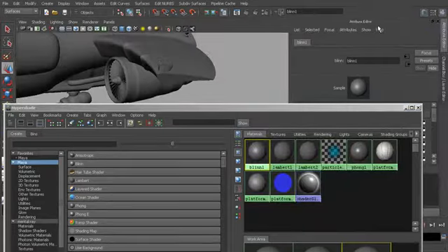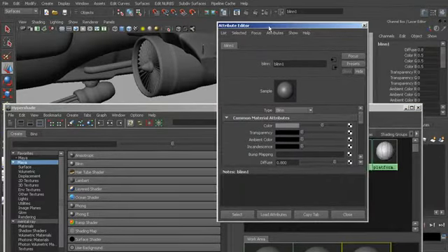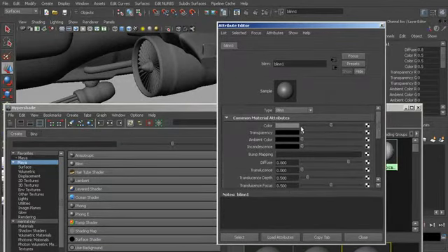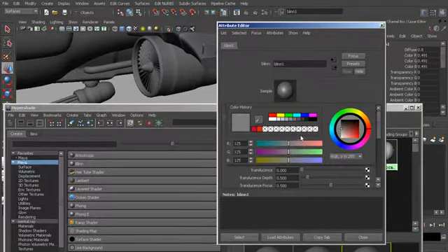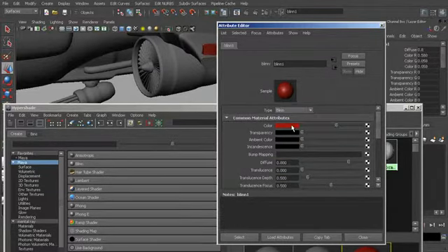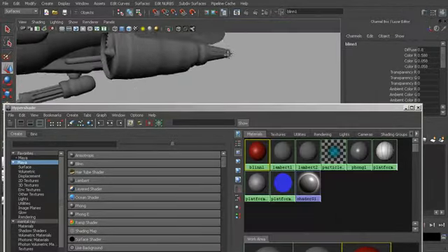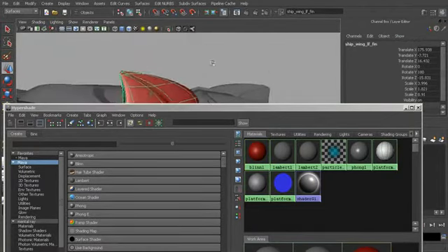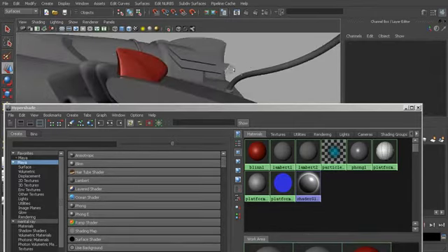We'll double click on the material to bring up its attributes, and then you can see in the common material attributes there are all of these attributes that we can change. Okay, at the very top you'll see one for color. We can dial the slider from black to white, change the value of it, or we can change the actual color. So let's make it red for now so that we can see it. So we'll change it to red, and you can see that that fin updates. Okay, so now we have this red fin that's a little bit shiny, okay, based on the specularity.